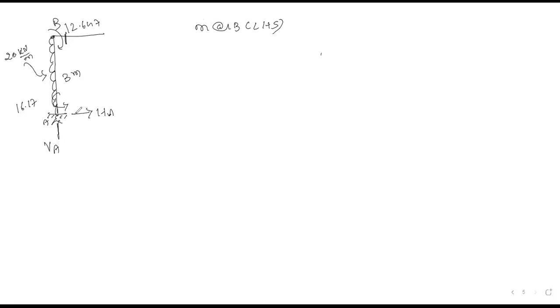So HA. Now what is moment? Moment equal to force into perpendicular distance. So to get a moment we need a perpendicular distance. Clear? So HA is acting in x direction and we have a distance from A to B in y direction. So can anyone tell me from HA and VA which force will create moment and which force will not create moment? Please students type in chat box.